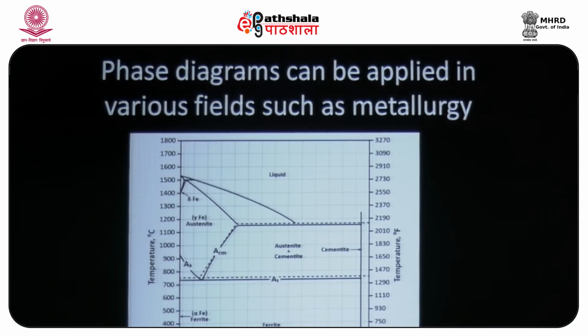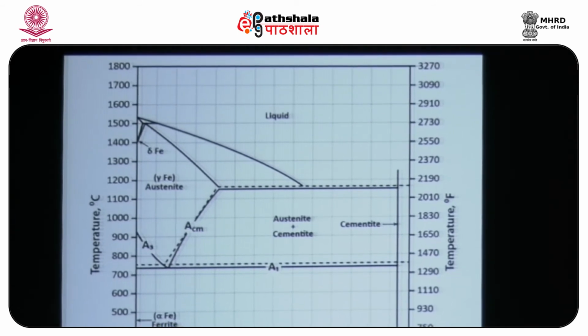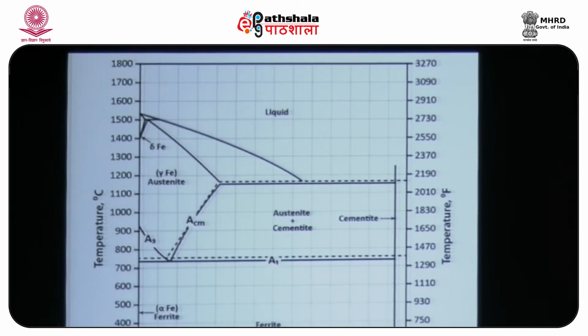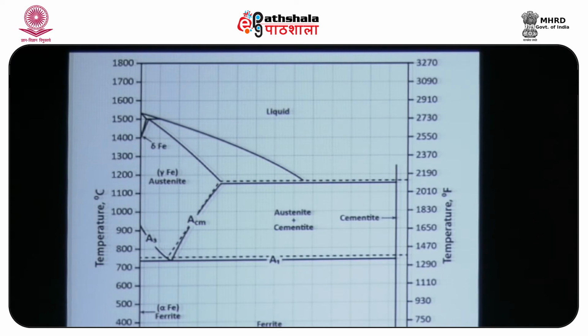So, for example, this is a simple phase diagram. Last time we said that on your X axis you have two different mixtures of A and B. Here you see the carbon weight percent on your X axis, and on your Y axis you have temperature. Same thing, this phase diagram was drawn based on experimental runs. They conducted experiments at each of the small grids you see, came up with the different phases that were there, and then came up with this diagram.